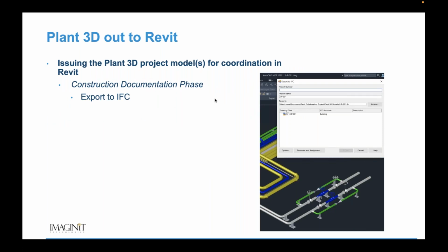And one of those other methods is to export my Revit model as an IFC file. If you're not familiar with IFC, it's the industry's data transfer standard for building model or object-based modeling technology. So you can take the object from one model format and convert it to something that another modeling tool will use to create a comparable object in its modeling format. Plant 3D unfortunately doesn't have the IFC import-export capability.